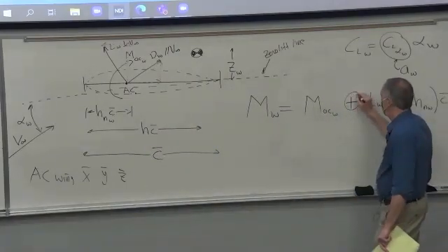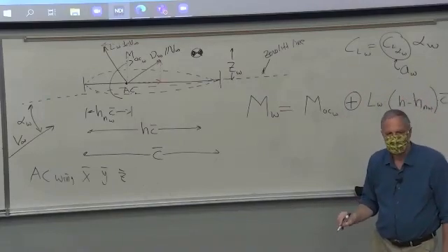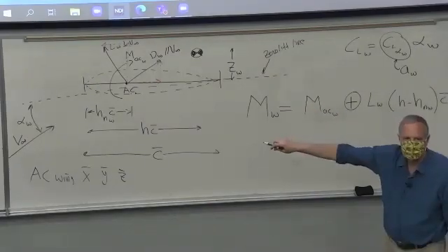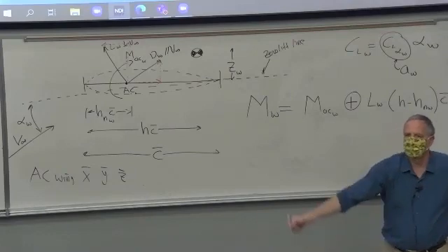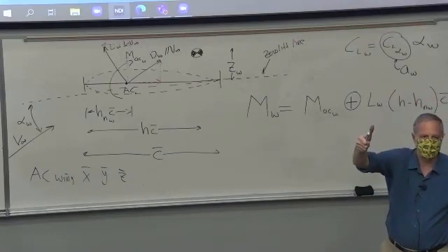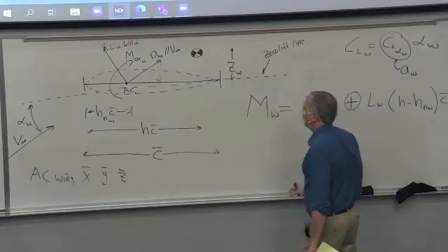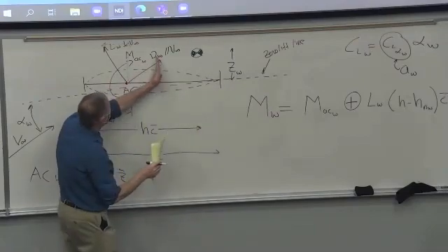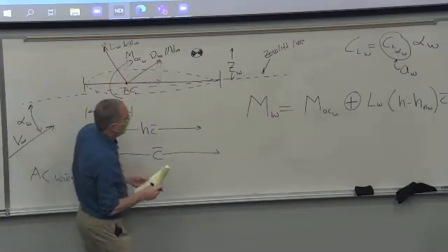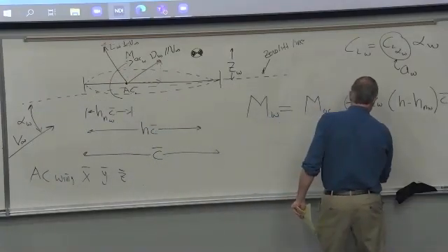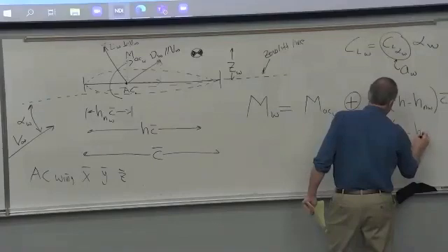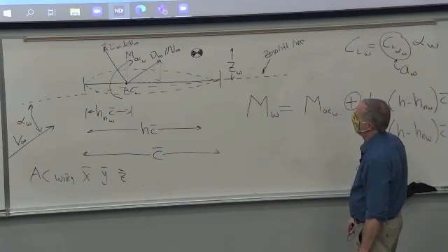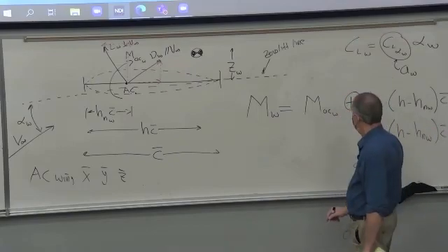And is the plus sign correct? We've defined AC in front of the CG, that's a positive distance. It's up, so that gives a nose up pitching moment, positive, right? Okay, got that one right. Then we've got the component of the drag up this way times that same distance. I've drawn it over here, but it's actually acting here, right? So I've got the drag of the wing times that same distance. And what sign do we put on that? Looks like a plus because it's up as well, right?